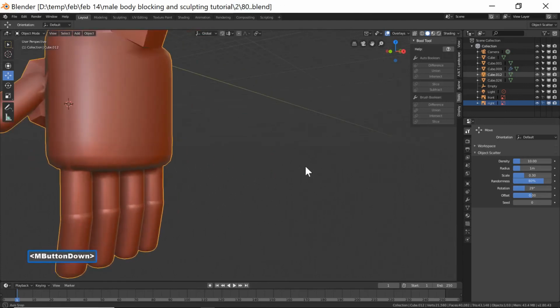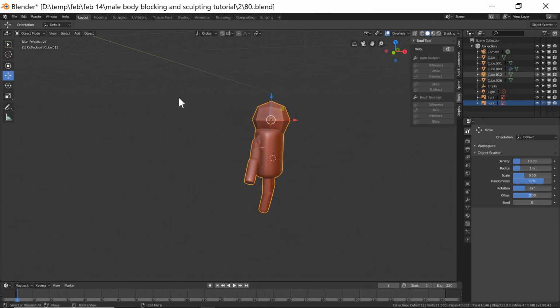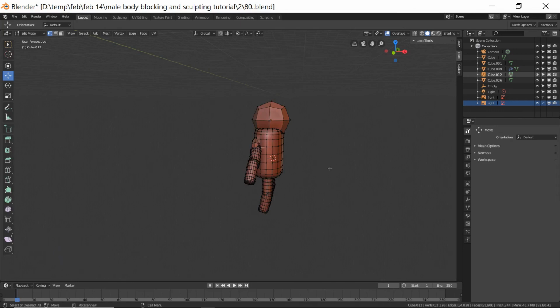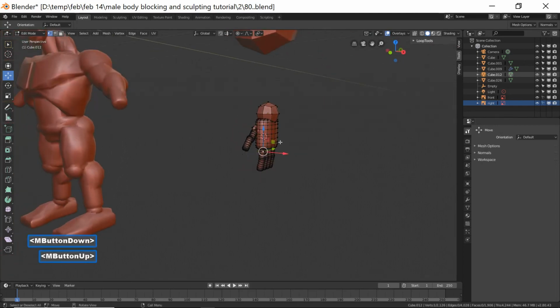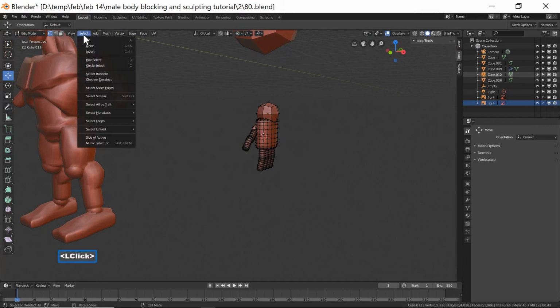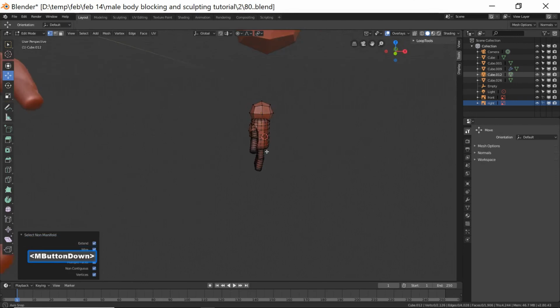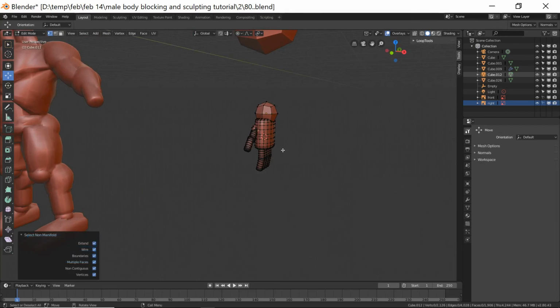Okay, when you click, it looks like everything is good, but you really can't tell until you go to edit mode. Make sure I'm on vertex select. Left click on nothingness to deselect everything. See how nothing is currently highlighted, right? So now I clicked off again. Now nothing is highlighted. So we go to select with vertex select on. Select all by trait, non-manifold. Now nothing is highlighting, and that is excellent because that means that we are good. This is a good Boolean union.